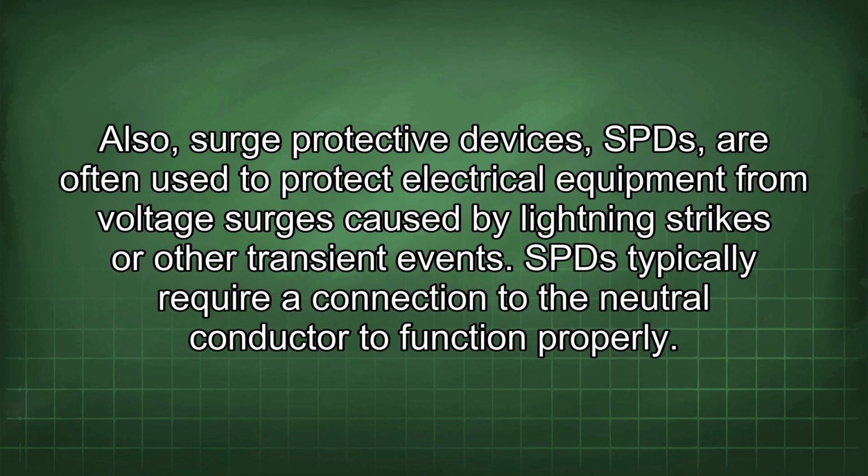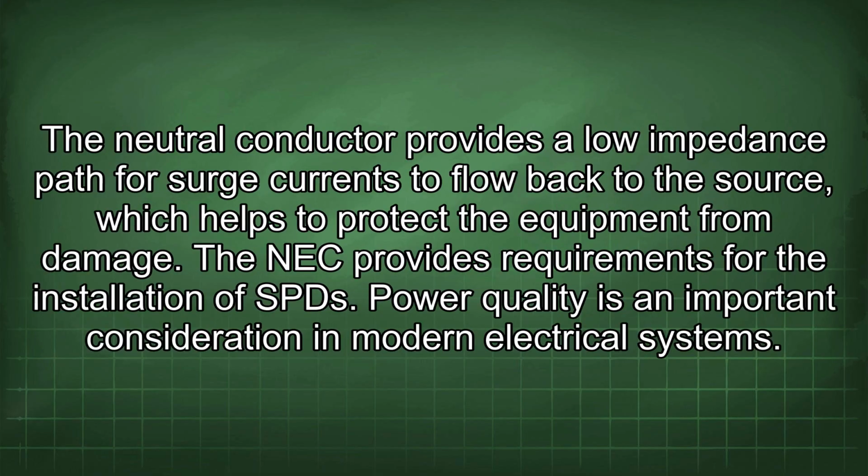Also, surge protective devices, SPDs, are often used to protect electrical equipment from voltage surges caused by lightning strikes or other transient events. SPDs typically require a connection to the neutral conductor to function properly. The neutral conductor provides a low impedance path for surge currents to flow back to the source, which helps to protect the equipment from damage. The NEC provides requirements for the installation of SPDs.